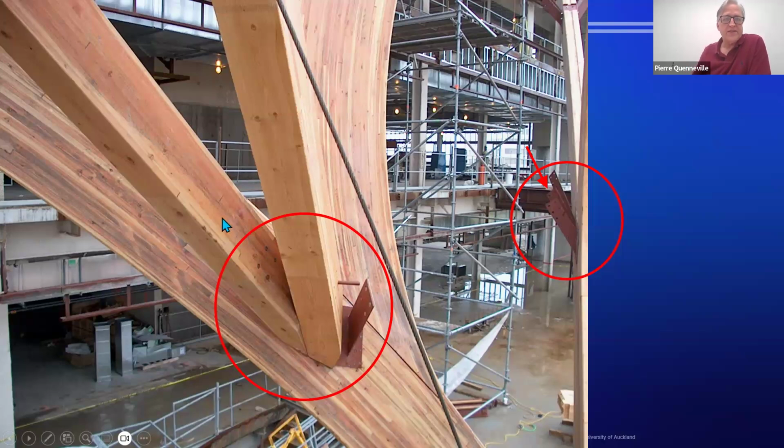The sequence of installation was very important in order to be able to insert those tight-fitting dowels, and the compression transferred from the member to the dowels to the steel plate would be designed using the EYM, the European yield model in this case. The plates were designed to avoid buckling.